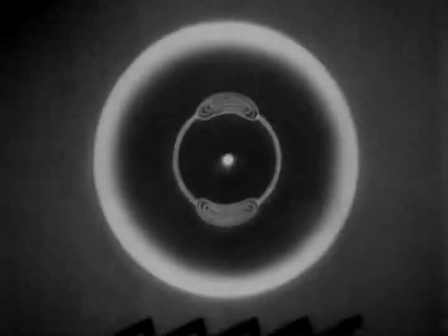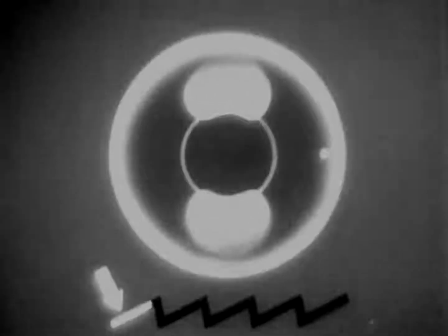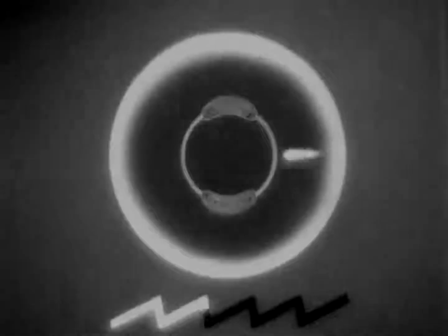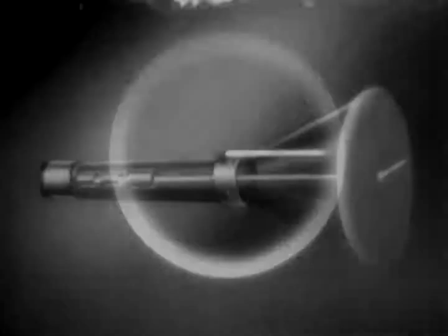When you apply current in the form of sawtooth voltage, you get the familiar trace and snapback movement of the electron beam. When it is speeded up, there's your PPI baseline, composed, as it was on the A-scope, of an electron beam sweeping back and forth so rapidly it creates the illusion of a solid line.